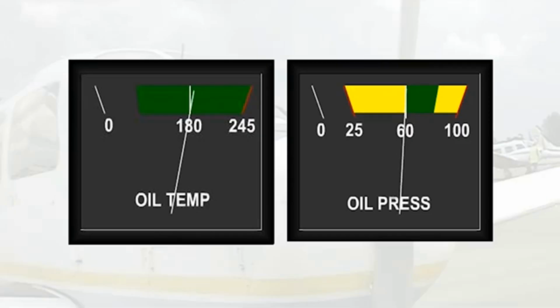Small fluctuations of the oil pressure gauge needle, either side of the desired pressure, may be indicative of a sticking pressure relief valve. This would cause the pressure to first build up beyond the optimum level, then, subsequently, when the pressure reached a point high enough to overcome the stiction of the valve, it would open, dropping the pressure momentarily below the correct level. Then the cycle would start again.